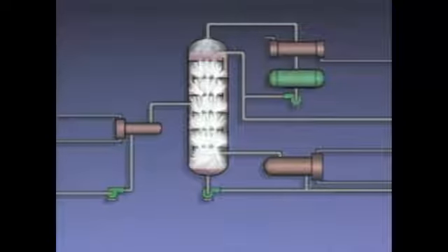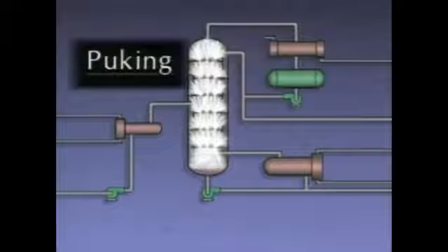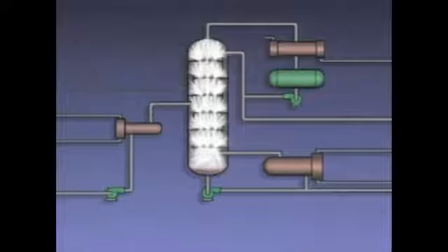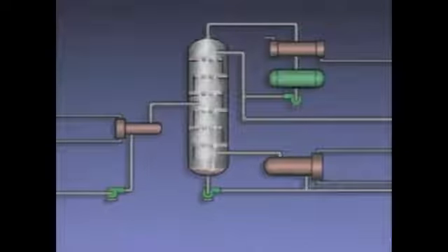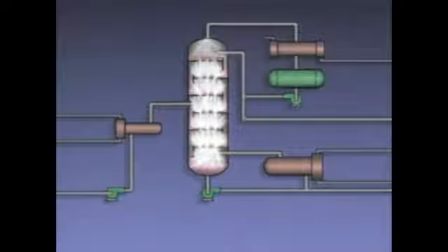If the problem continues, the pressure of the impeded vapor can increase to a point where it forces liquid out of the top of the column. This condition is sometimes called puking. When the vapor pressure is relieved, liquid flows back down the column, and the pressure buildup begins again. The surging of liquid up and down a column can sometimes damage internal structures of the column.